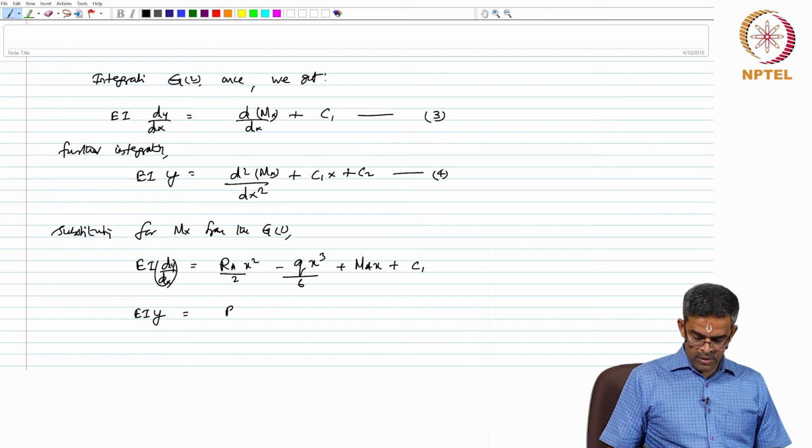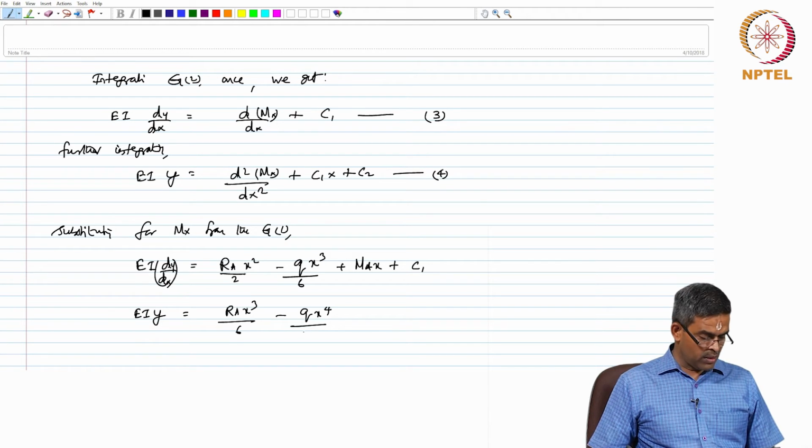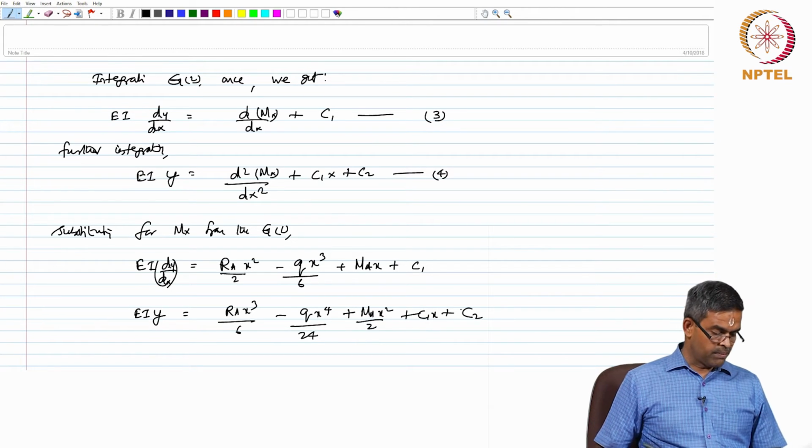EI y is Ra x cube by 6 minus q x 4 by 24 plus Ma x square by 2 plus C1 x plus C2.